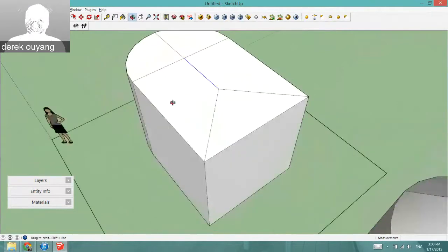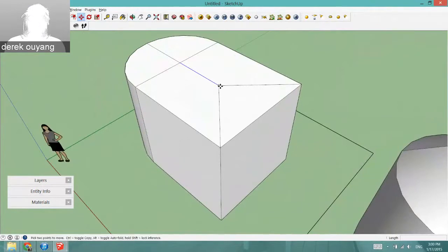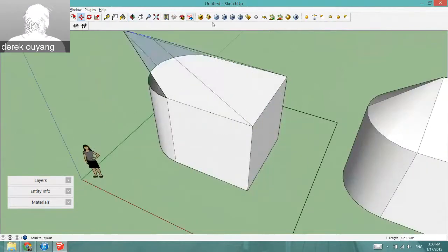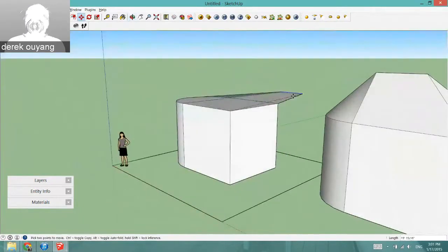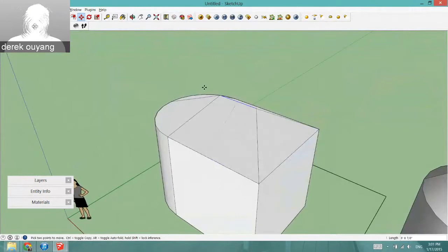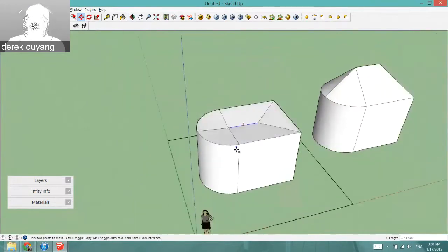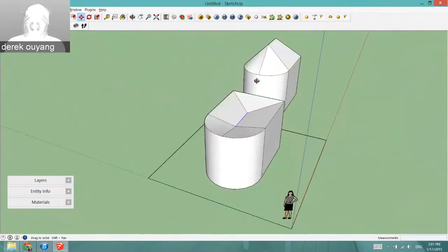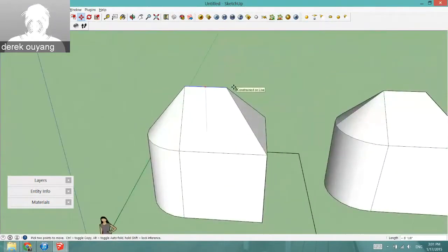So if we just select the ridge and click move and go ahead and grab the midpoint or any part of this line, you'll notice that in fact the stickiness works, but SketchUp naturally thinks we're going to be working in this plane, so we have to physically tell it no by locking to the blue axis, so clicking up or down. And you can see immediately from there all our stickiness ideas were correct, and we should be able to specify any height from here. But for the purpose of completing the model, let's just go upwards 5 feet.